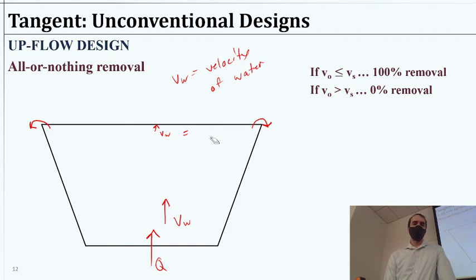What I'll say is the velocity of the water is essentially V naught in a way, but it's negative V naught. And so if the particle settling matches that, it'll just barely not make it over. And if it doesn't make it over, chances are it'll collide with some other particles. In reality, it would stick to them probably, and then they'd form larger particles and start sinking.